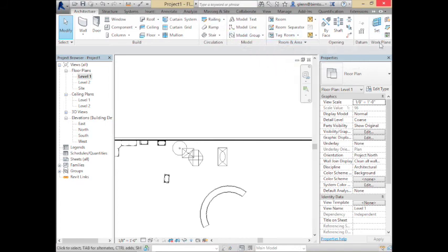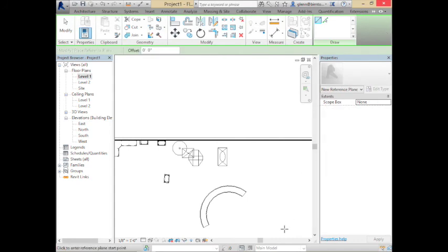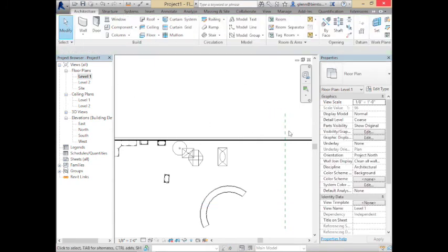And there's this notion over here, it's way over on the right-hand side of the ribbon. It's called the work plane section. And there's something that lets you draw a reference plane. So let me show you what it looks like. You're basically going to just choose that tool. I can either pick or draw. I'm going to draw. I'm just going to draw at some arbitrary location out here, a vertical line or a line that will kind of define a plane that will cut vertically as opposed to horizontally. So that's my reference plane.